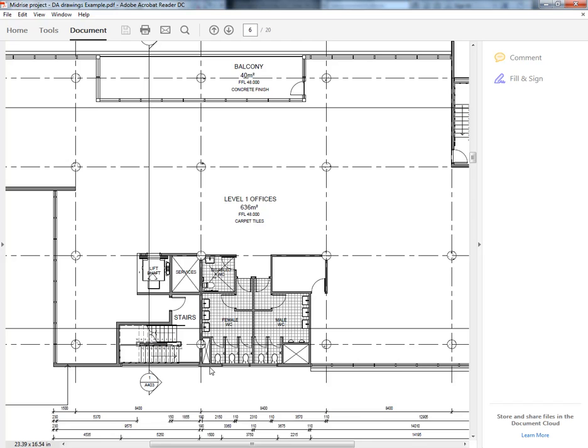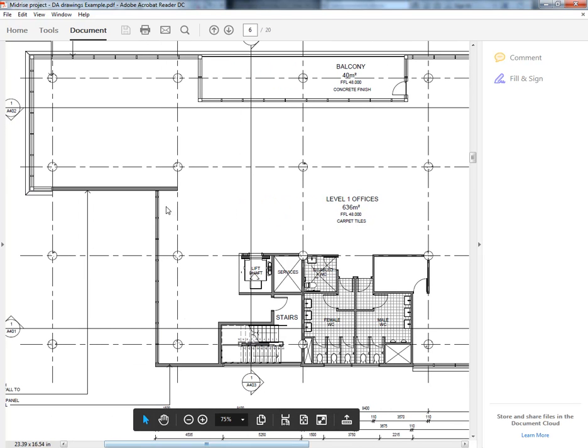When you're doing the floor plates, don't be too fussy about the shape of the edges. Even just a rectangular floor to begin with for each one, and it's often easy to then change the shape. Having that floor in section is going to help you a lot to establish all the overall heights and connections between things. So shafts, all those things, you can't really do until you've got the floor. So I won't say any more. I'll just give you some time to try all those things.